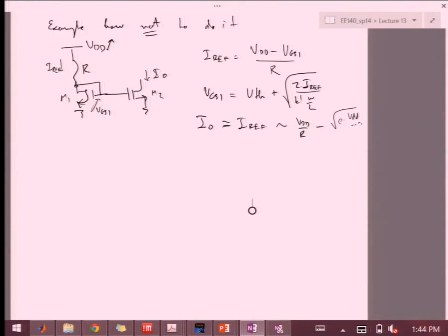Okay, thermal voltage is a good idea. I will show a few designs later, but you would need to have bipolar parasitics and things like that. But if you're lazy, and you don't want to mess with building a band gap reference, what can you do quickly here in terms of MOSFETs?